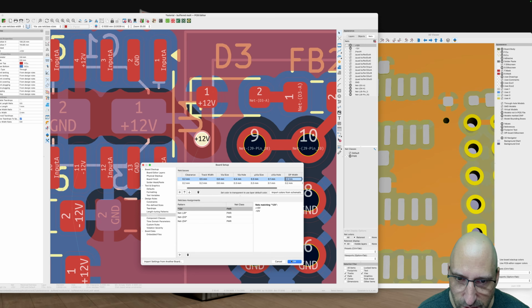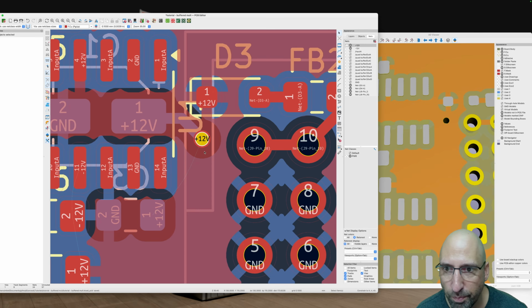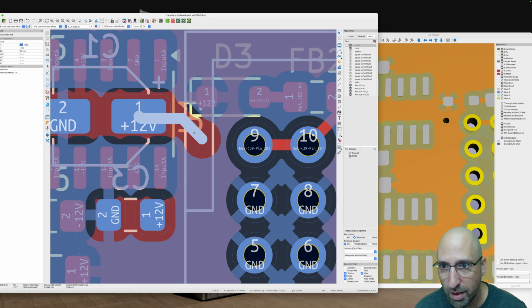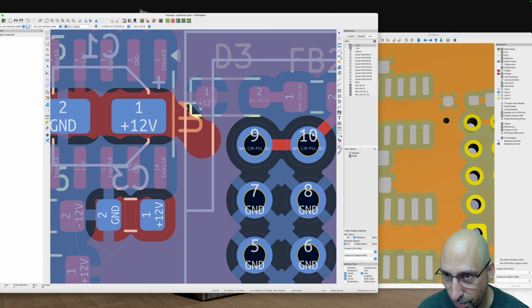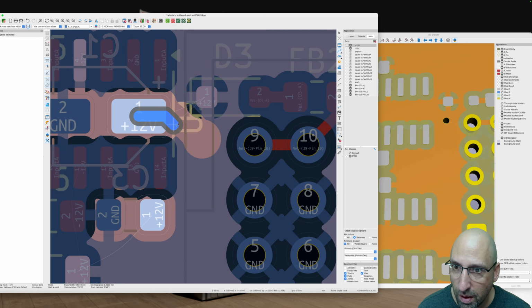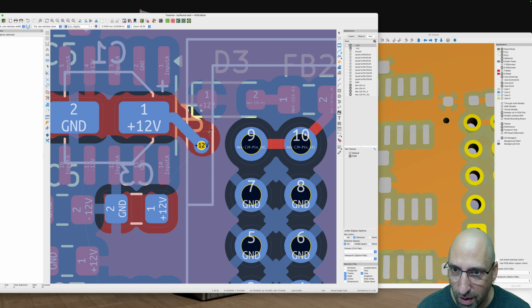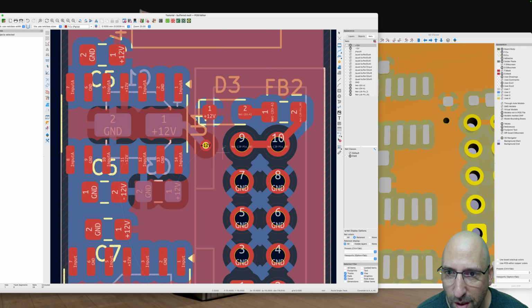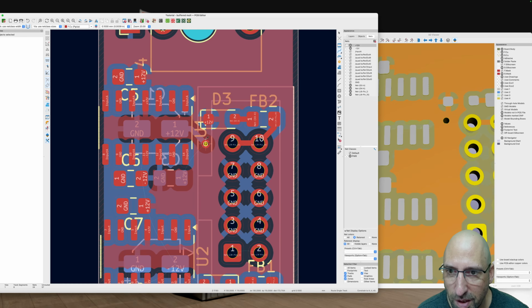So that should give us a bit of a bigger, just delete that. Switch to the back copper with V. Hit U to select that whole track. Try again. V. That's looking better. And still, I'm not seeing it connect to the front copper.